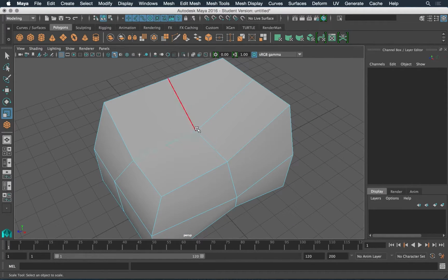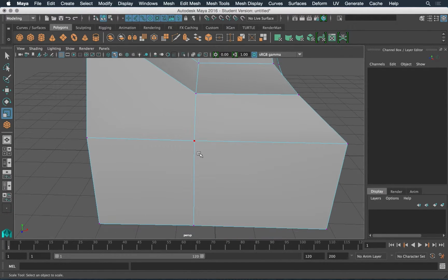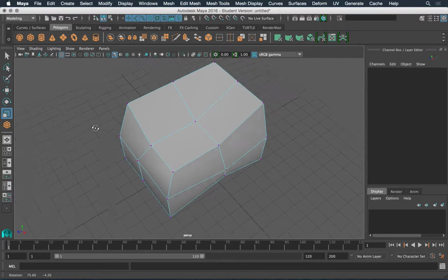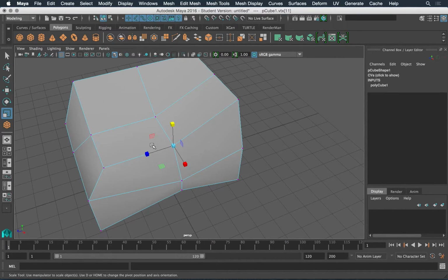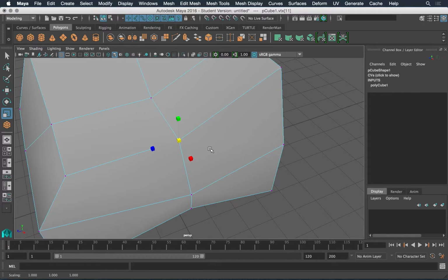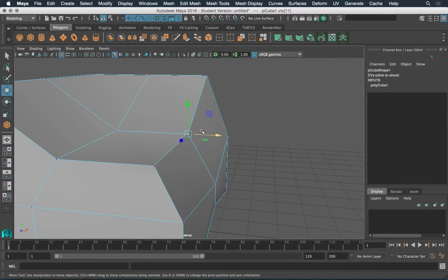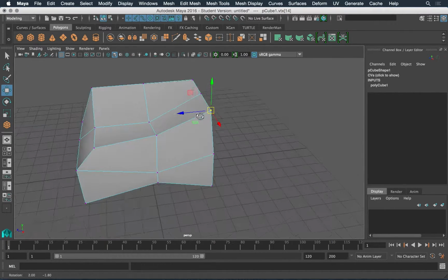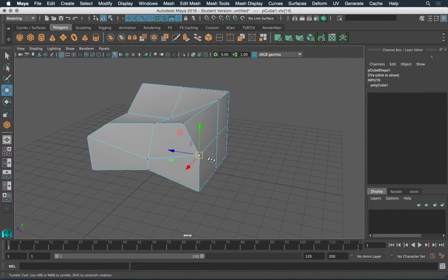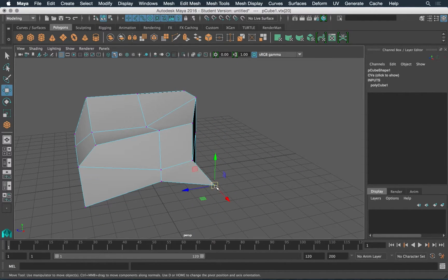Vertices are the same. So I'm going to right click, go to Vertex. Now the dots, again the vertices at the crosshairs, turn pink. Okay. You can click on them. The only difference with vertices is that you cannot scale them. The scale tool will be there, but nothing will happen. Okay. You also cannot rotate a vertex. Vertices can only move. Because again, they're a point in space, like a pixel. You can't rotate these points. I'm just going to move it around. Okay, so you can adjust all of these. Just, again, experimenting with it.